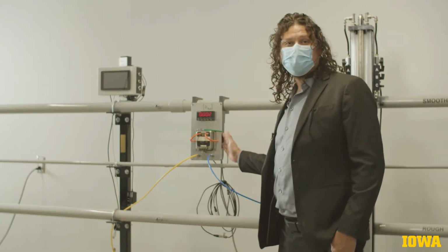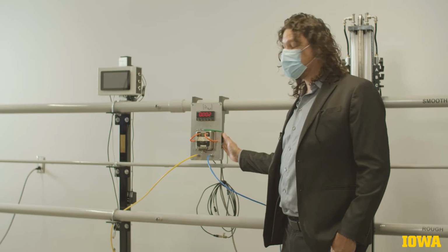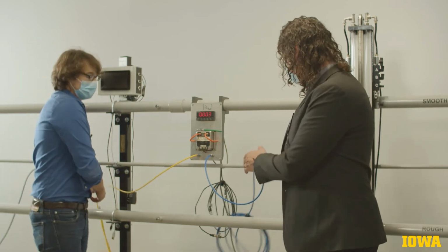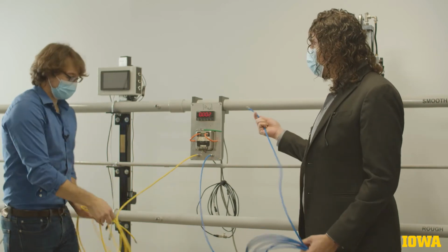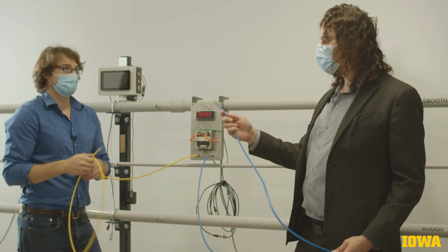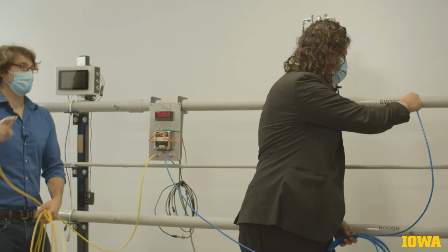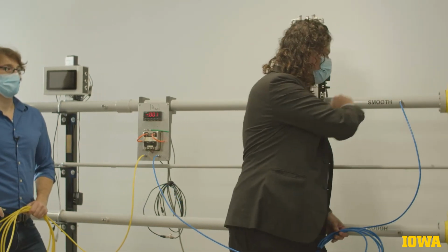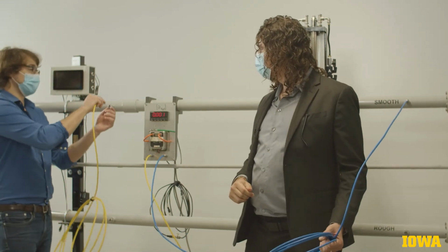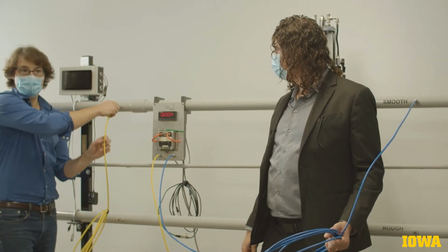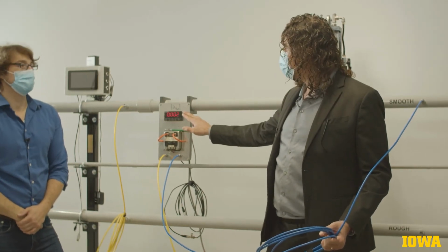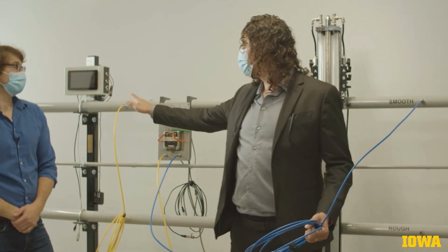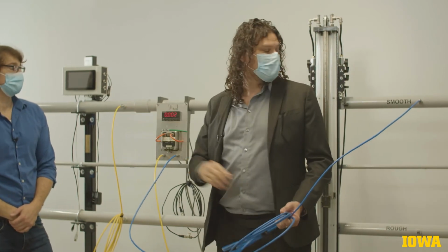Our device here uses electronic pressure transducers, and we have set it up so that we can change the locations where we measure pressure. We can connect the low end to one part of the pipe, and the high pressure end can be connected to a tap that is upstream. So when air is flowing, the pressure transducer is going to give us a reading of the difference between the pressure at this point in the pipe and the pressure at this other point in the pipe.